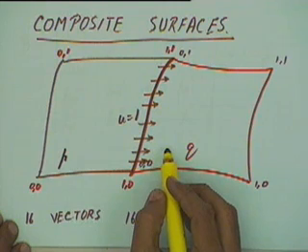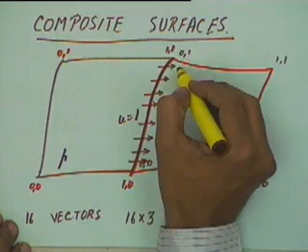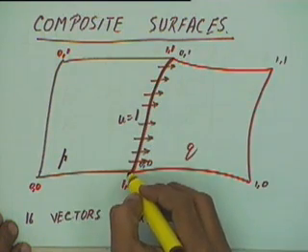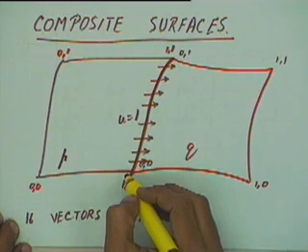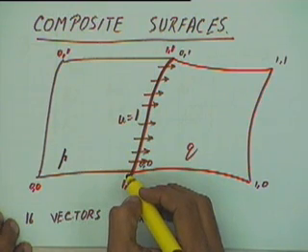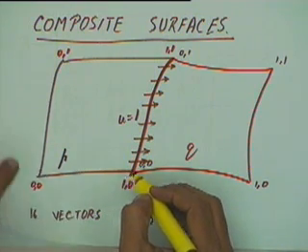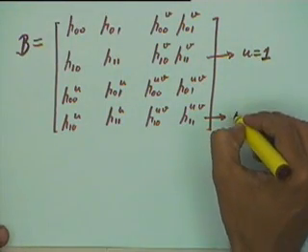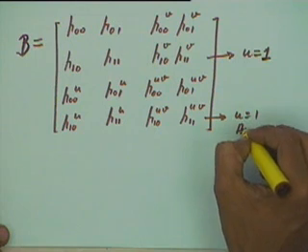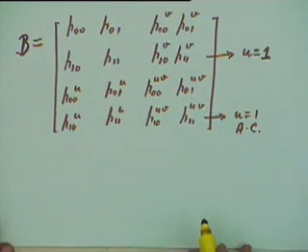Only then we will get C1 continuity. The tangent vector along this curve is given by the auxiliary curve corresponding to this curve, the u equal to 1 auxiliary curve.